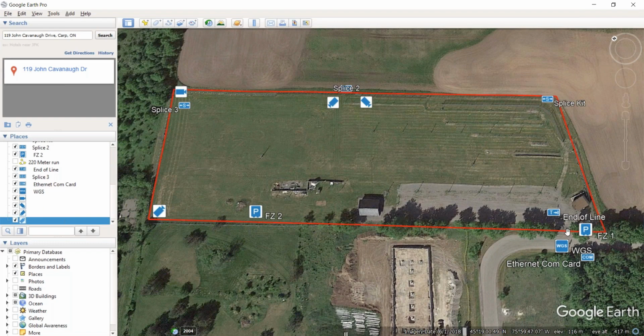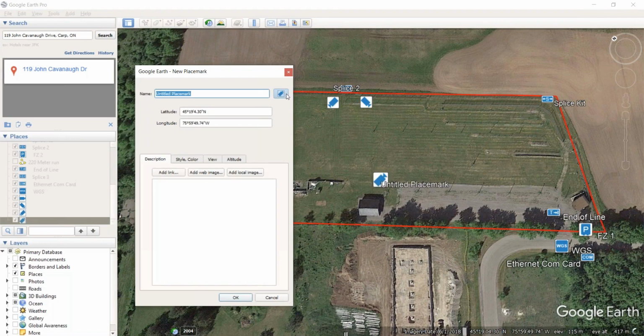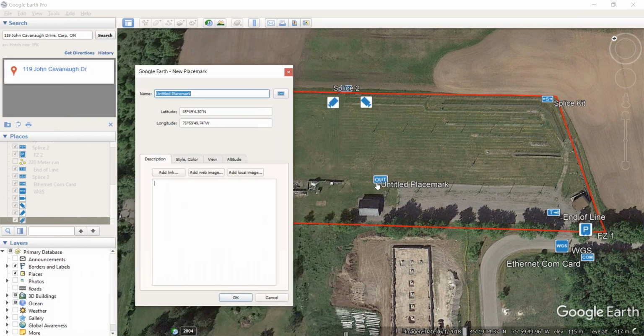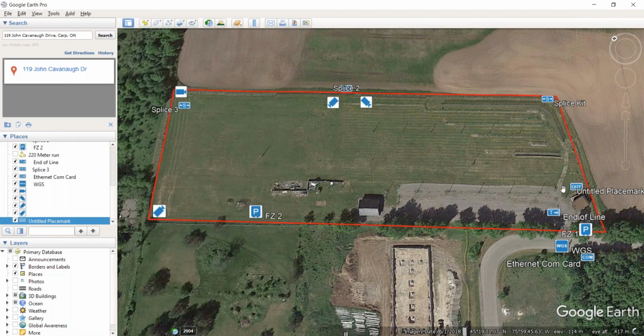Now, one last thing that I do want to touch on is if we do not have an ability for a software integration, one of the unique things that Senstar has is we also have additional tools to bring in dry contacts, i.e. an output card. So I have an option that if it's just 4 cameras, I could drop one right on a processor, and that's 8 cameras or less because we have 4 IOs on board. But one of the things we do have is we have an Ultralink, and we drop these inside our network cabinets. It provides you 8 in or 8 out. And then what we find is we had a 32 output expansion card, and that's how we bring a lot of cameras into place back into the control room.